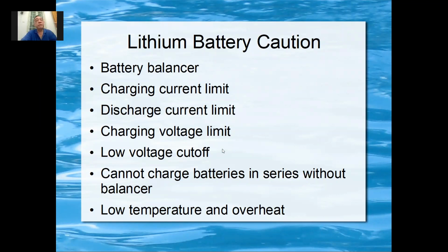So when the battery runs too low, then you also must cut off. Let's say for a 12-volt battery, you run until 10 volt, you must stop already. Below 10, you have to stop, because if you don't stop, then the battery will get damaged. You cannot let the battery run like our alkaline battery, run until flat, then throw away. This one cannot. You run until the voltage is too low, you must stop.